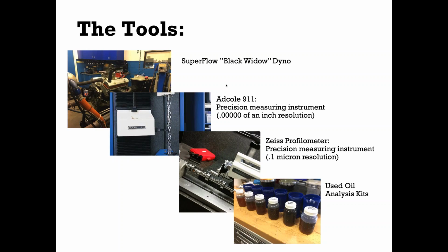If you're feeling sick, you go to the doctor, what are they going to do? They're going to take your blood. Why? Because it gives them a chance to look inside you and see what's going on without cutting you open. Used oil analysis lets you look inside your equipment without pulling it apart. It's a great, great tool. Tells you the health of the engine, as well as the health of the oil itself. So that's, again, a great tool that we use a lot.